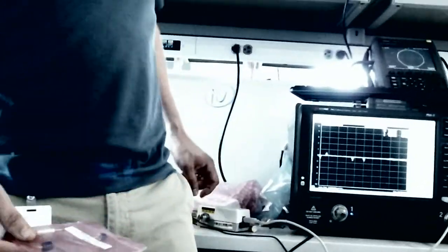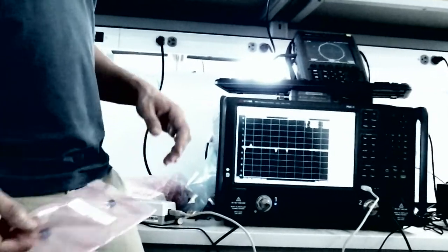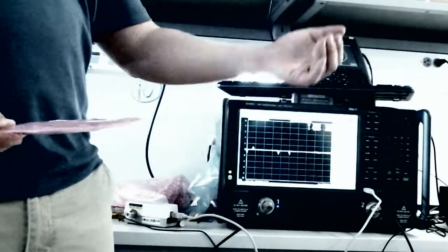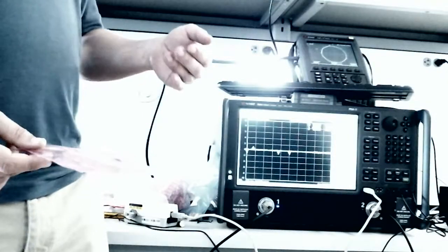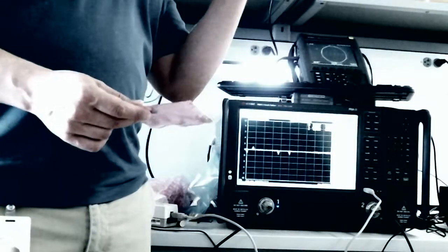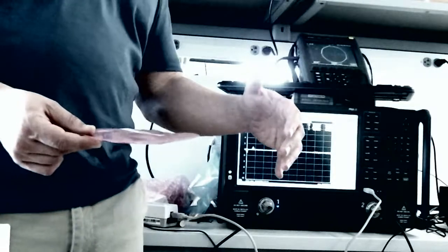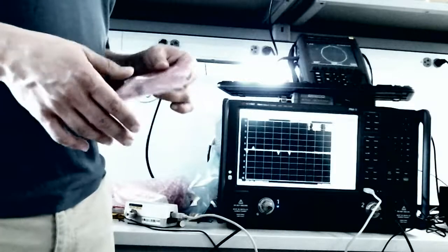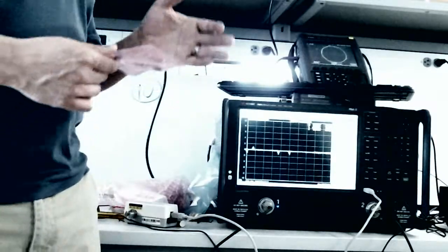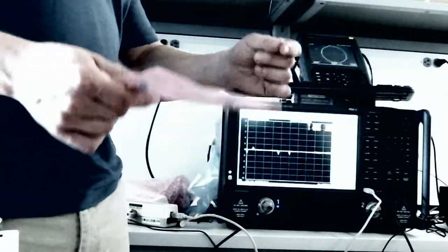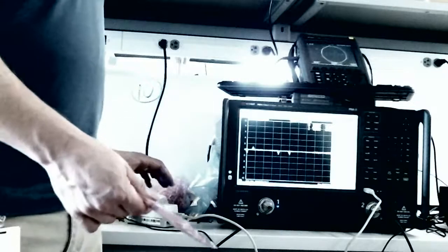And what this will do is, remember how I said there's a number of different impedances inside this device? There's about 7. So it will set itself to different impedances and sweep around the Smith chart so that when you do your noise figure measurement, you can get true 50 ohm noise figure, right? So if you have a device where you know it's not exactly 50 ohm, but it's around 50 ohm, maybe it's 48, and you really want to know what's the exact noise figure if this device were 50 ohm, you would use this as part of that.